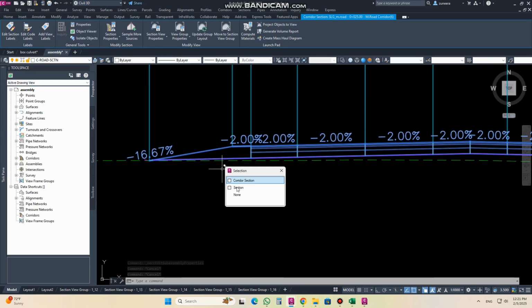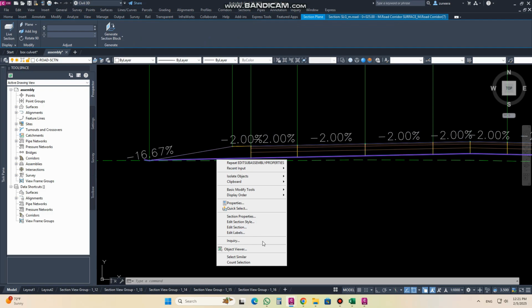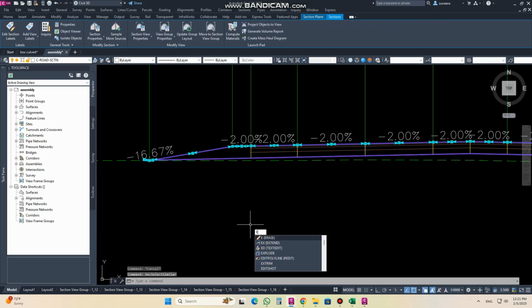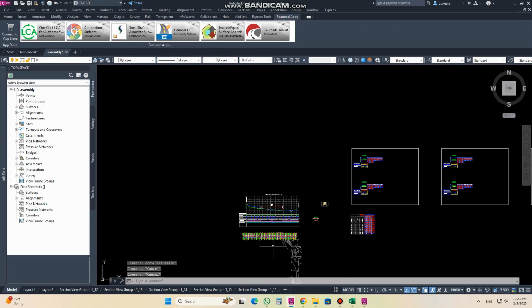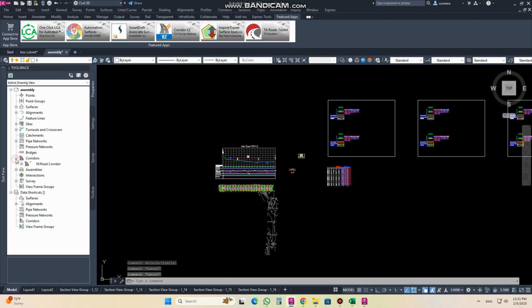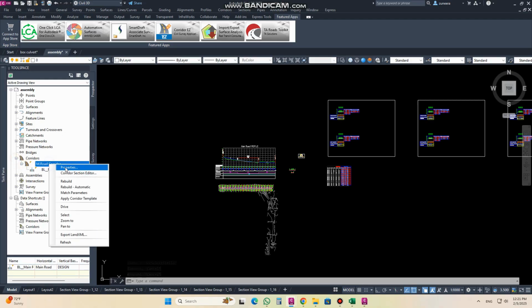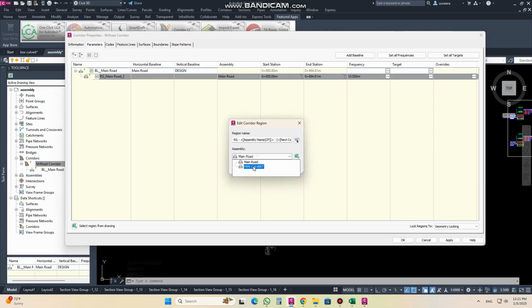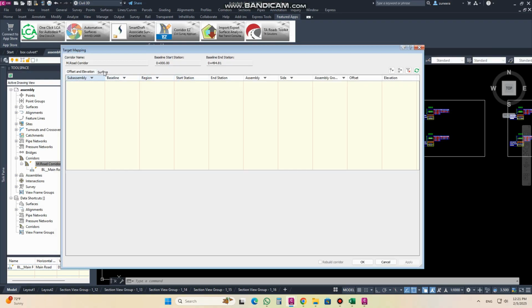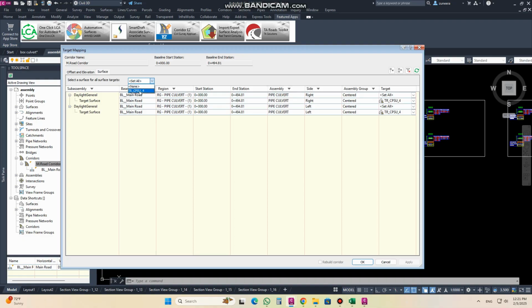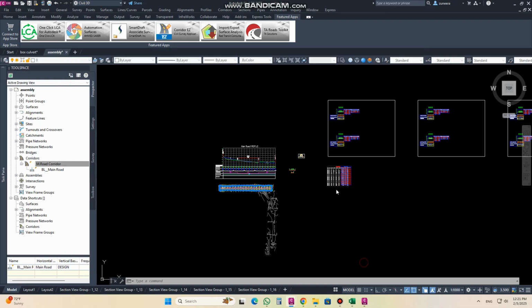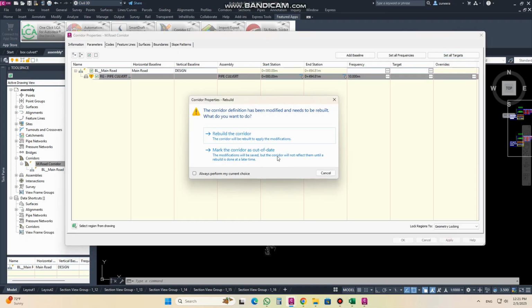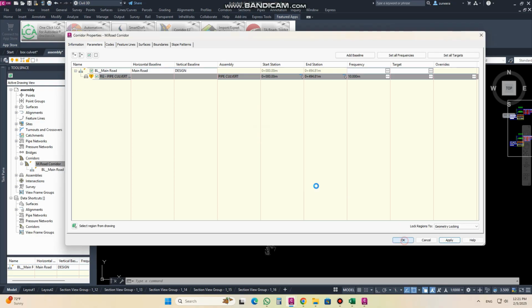As you can see, we created this before for the road. So we'll replace this assembly in this cross section. From the assembly we will select the pipe culvert and from the target we will select the natural ground surface. So click OK.